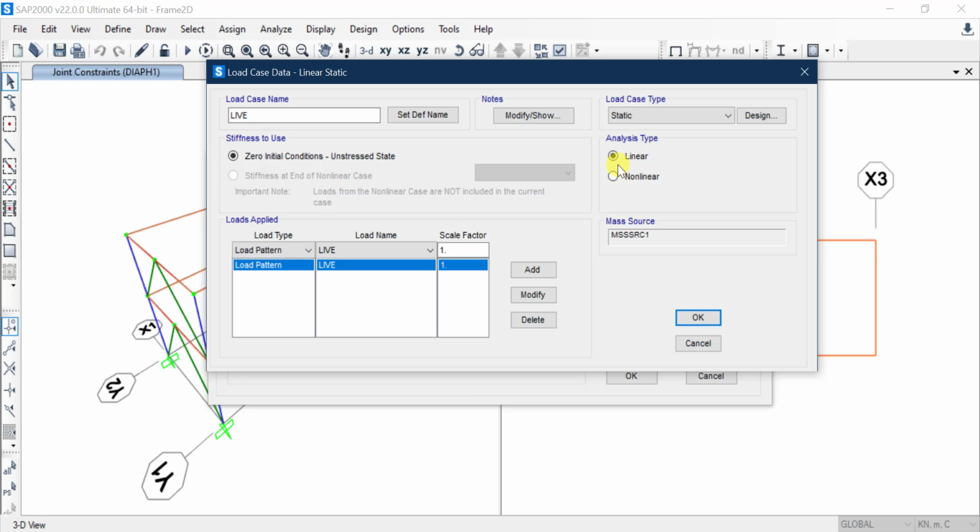Well, in any structure analysis problem, you have two types of nonlinearity. When you do any structure analysis, you have two types of nonlinearity. The first one is material nonlinearity, meaning that if you have, for instance, steel, steel can be elastic if it has small strains and deformations. But if you have large deformations and so on, it can become plastic and it can yield. So this is material nonlinearity. Okay.